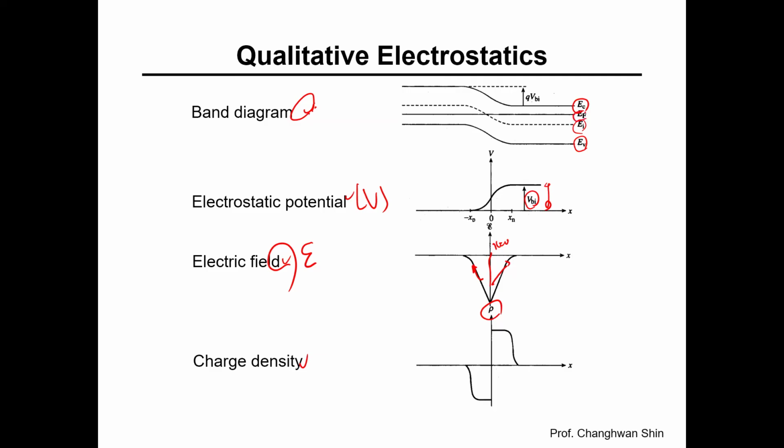The Fermi energy level, denoted as E sub F, remains constant throughout the device at equilibrium. So imagine these bands as layers of a landscape that get bent downward like a water slide going from the N to the P side. This band bending creates energy barriers that affect how carriers move across the junction, which ultimately determines the electrical characteristics of diodes and other devices.